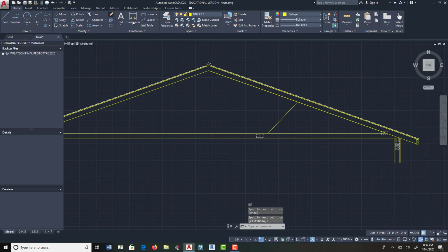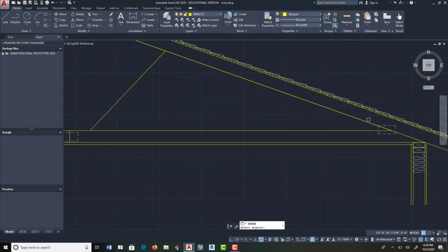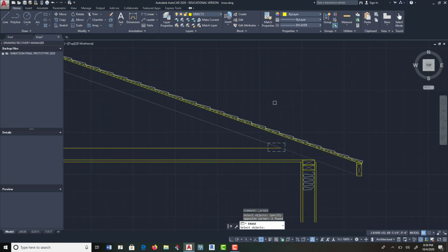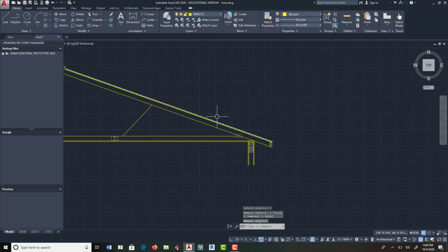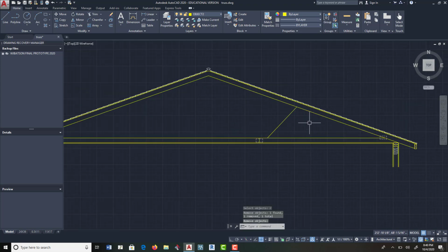So now, don't forget, let's erase that line you put in there. And it's a double line over there, so you just cross over there and then remove, R, enter, remove this line from the selection, and then it'll go away. There you go. So now you got the half and a half, and you got a third and a third. And this line is going to come down and join that.